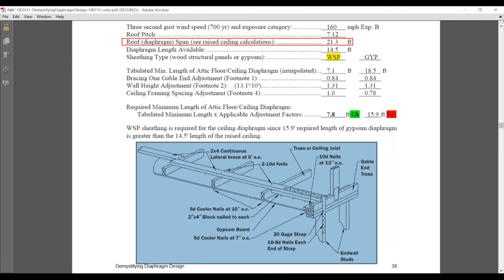I'll get to those calcs in just a second, but the other thing I want to point out in this diagram before we move to the next page is making sure that we can transfer those end wall loads at this hinge point. So where the stud wall frames into the gable end framing or gable end truss, we've got a hinge that can form. So we could have either windward loads that put this in compression. We can have leeward loads that put this wall in tension.